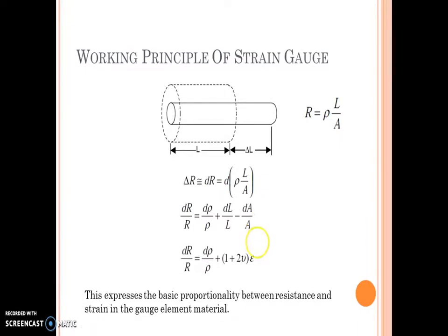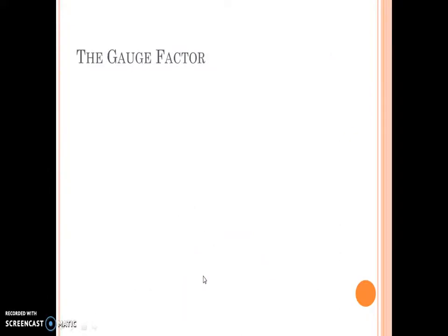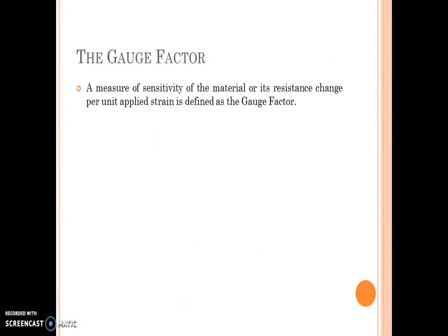So this is like maintaining bridges. As I told you, these are strain gauges which are mounted below the bridges. Now if you want to measure lateral stress, they are also connected across the columns which are raised while constructing the bridges. So the output of these strain gauges can be monitored. This is something people might have been doing in olden days.